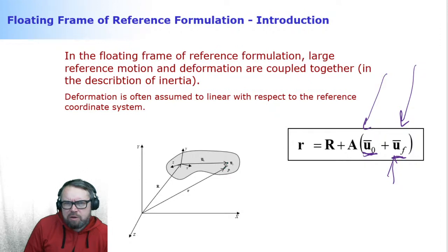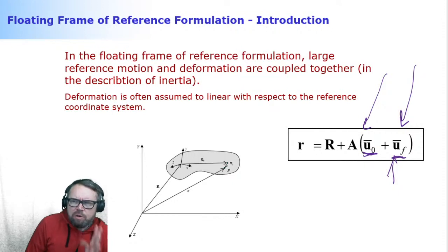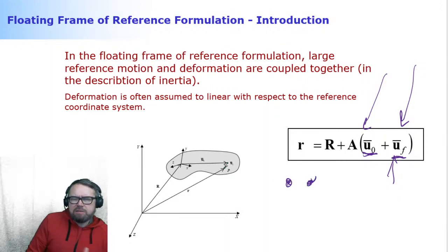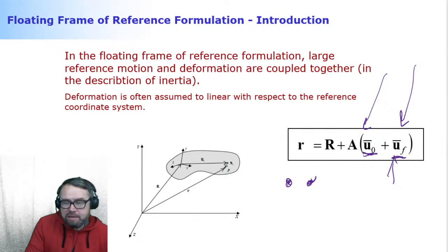We simply do not have the computational power to take all the particles into account. So what we will do, at the end of the day, is take each of the particles into account, but limit the way they can deform with respect to each other. And that's what is called discretization. So we are saying that neighboring particles cannot go however they want, but there is a certain number of ways that they can deform with respect to each other. That's how it goes.